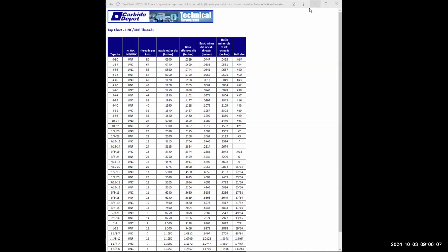Enter. I'm going to select this line, this line, this line, this line, this line. Enter. Type in P for property. Enter. Type in LT for line type. Enter. Type in hidden line. Enter. Enter again. Now, I'm going to erase this line.